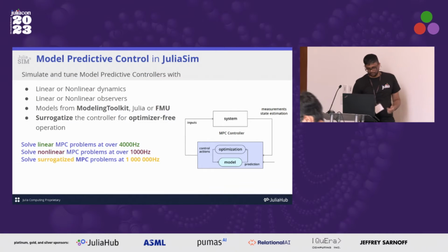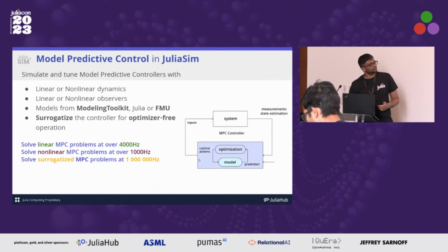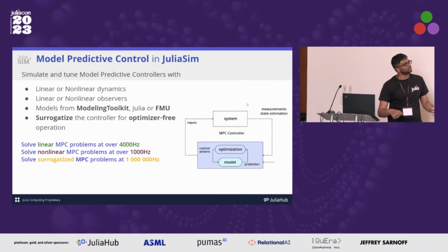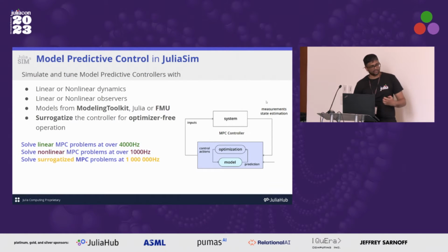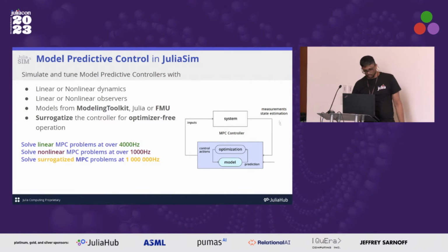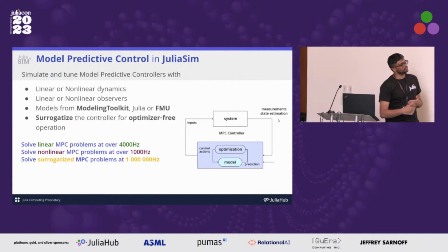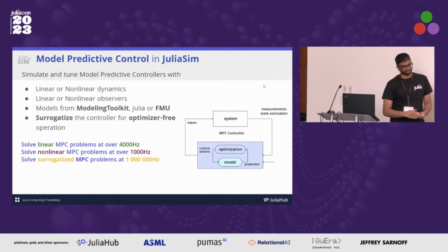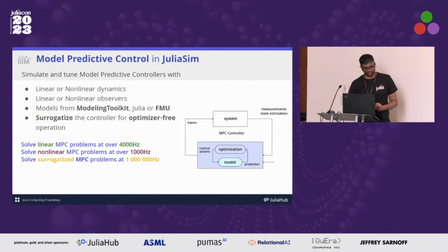And then once you get these control actions from the optimizer, you would pass the first of these control actions into the system, which in this case is the actually deployed real-world system. And at the next time step, you would get a measurement from that real-world system, which in general you would not be able to measure all your states. So there would often be a third step, which is state estimation, which is some sort of Kalman filter or the nonlinear variants of this.